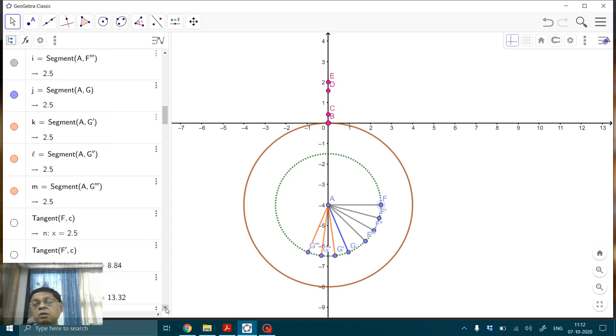So now, remember that this offset circle, the follower axis, the translation axis is basically tangent to this circle. So you can see that. So here is the tangent that is drawn. I'm just showing you that tangent so that you visualize. So remember that the follower is basically going to move up and down this line. Okay, I'll hide that.